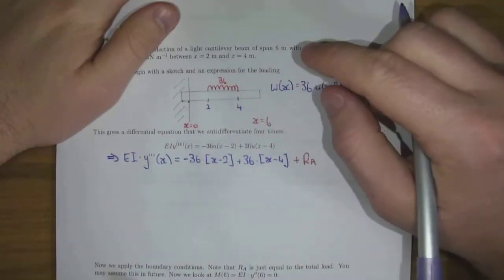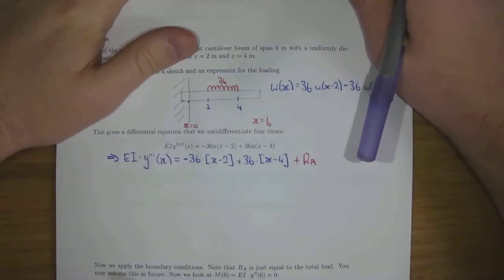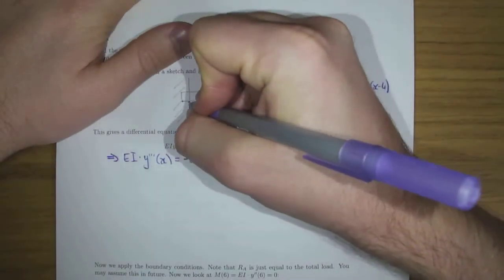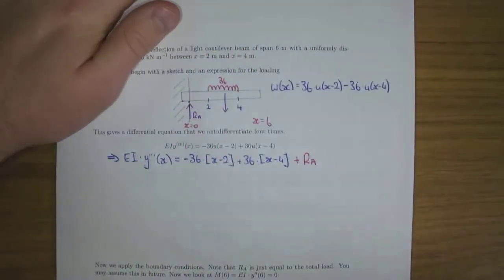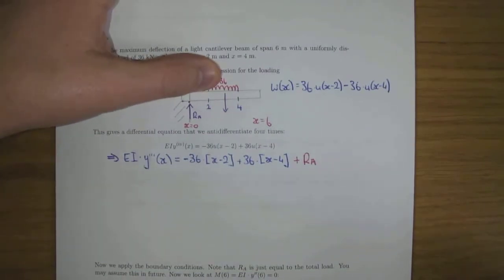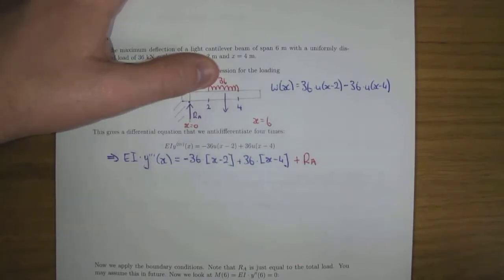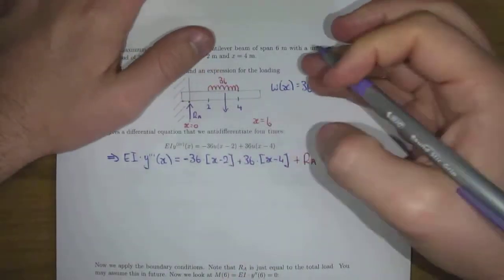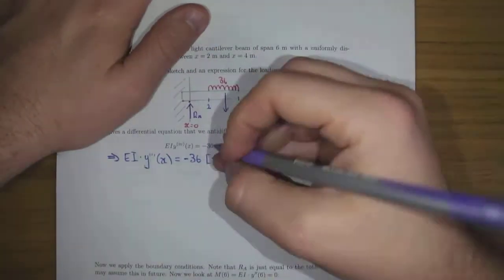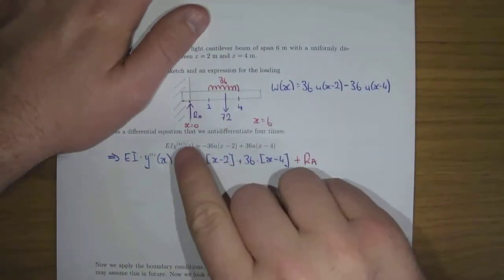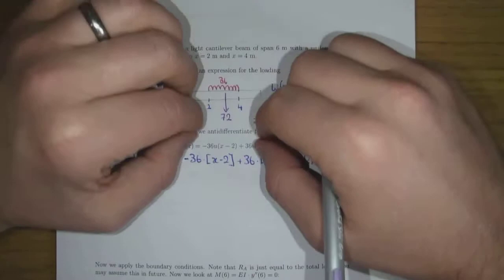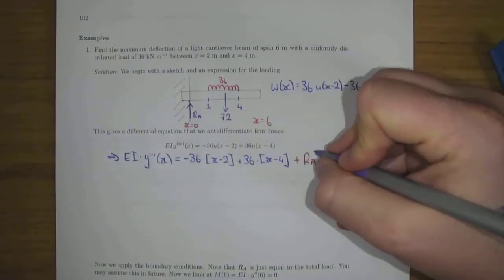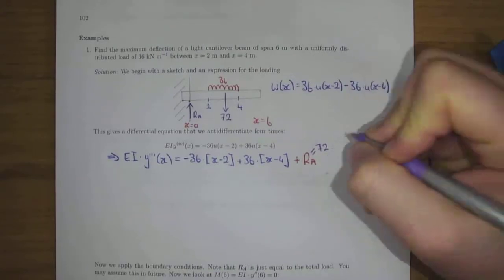So if it's in equilibrium, the sum of the forces must be 0. And the up force is RA, and the down force is the load. And remember, this isn't mass here, this is actually weight. So the 36 kilonewtons is an appropriate m times g. Now here you've got 36 kilonewtons per meter, so you've got 36 there, so it's 72 in total. So you've got 72 going down, and for it to be in equilibrium, RA must match that. Because if 72 is bigger, the beam has to go down because there has to be an acceleration. So RA is equal to 72.